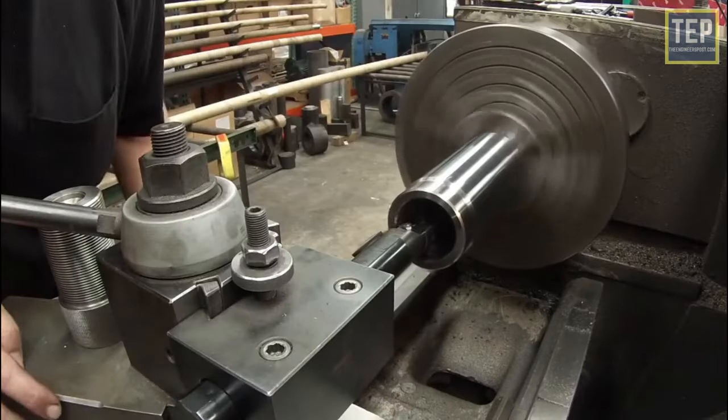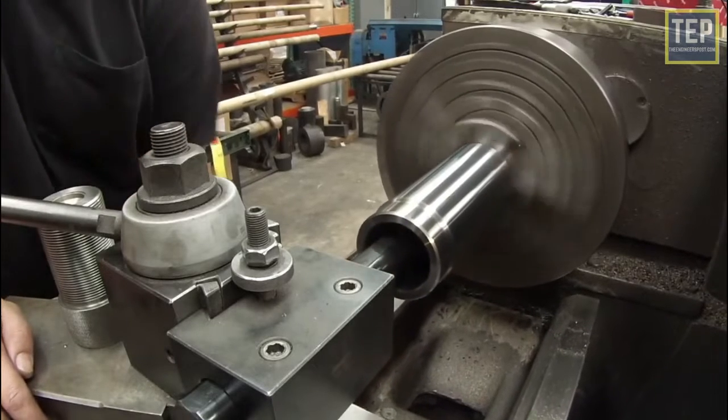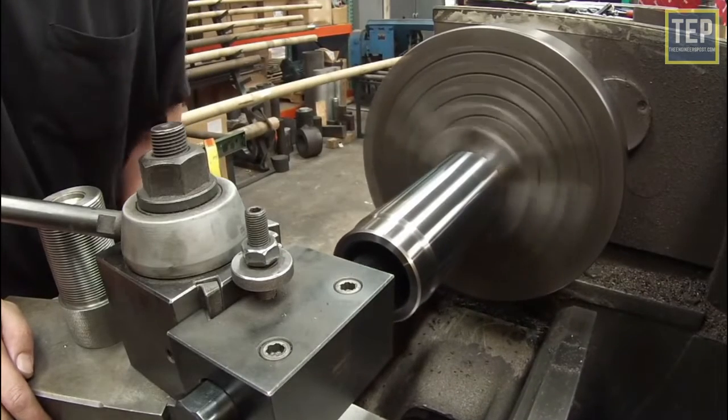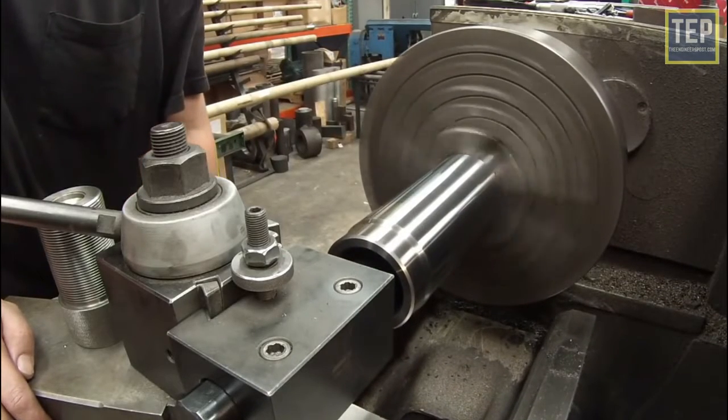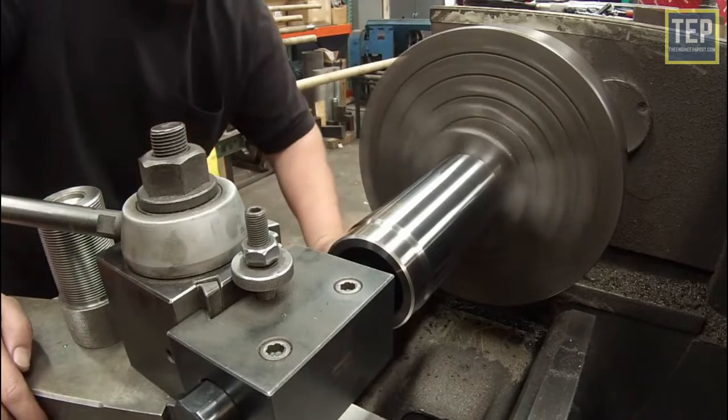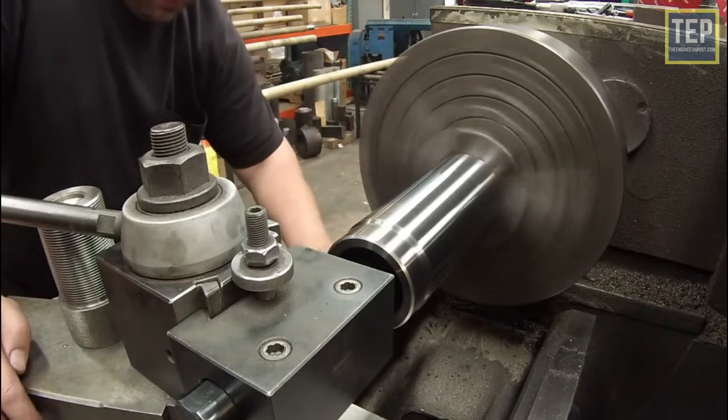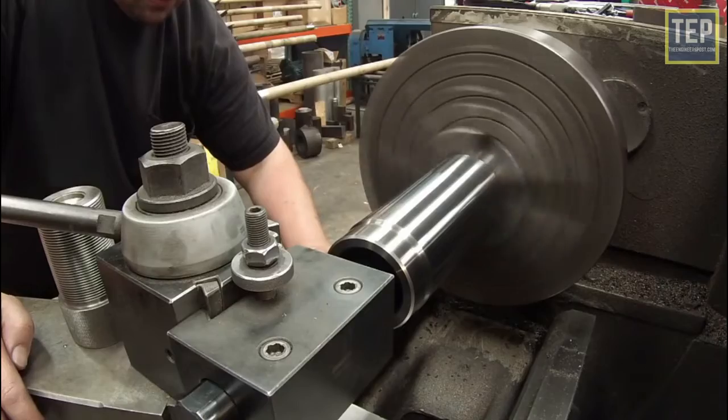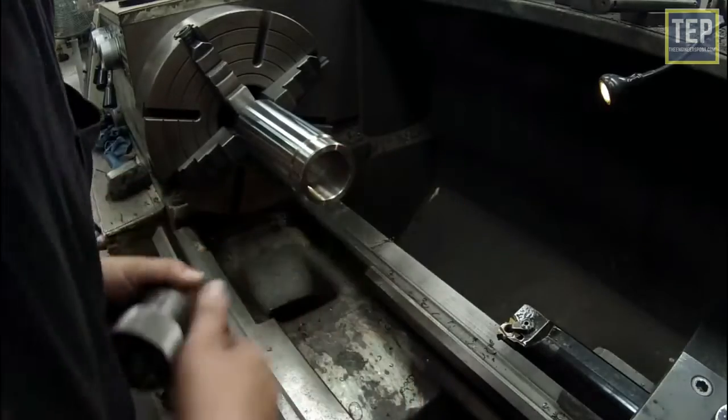Internal thread cutting tool. The cutting edge of the tool is exactly similar to an external thread cutting tool, but the front clearance angle is sufficiently increased, as in a boring tool. The tool is a forged type, or bit type, and held on a boring bar. The point of the tool must be set square with the work.